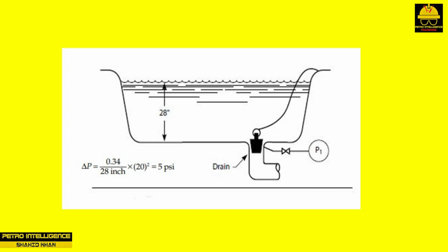Of course, we all see this happen several times a day, typically when we flush a toilet. So much air is drawn into the water drainage piping that we install vents on our roofs to release this air. The only requirement, then, for vapors to be drawn into a flowing nozzle is for the nozzle exit loss to be larger than the static head of liquid above the nozzle.